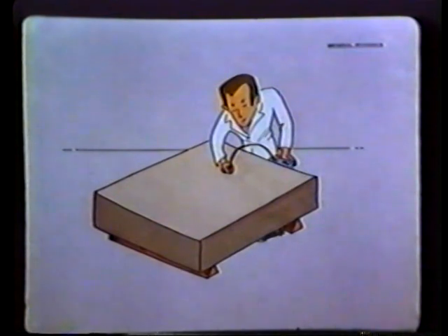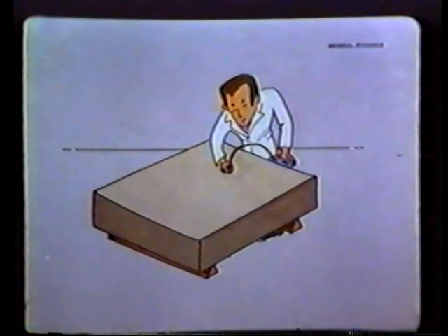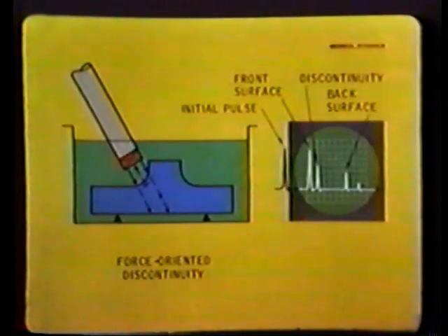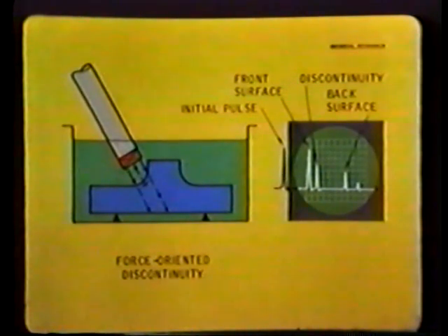The experienced operator develops a knowledge as to what type of discontinuities are likely to be encountered, and where they're most likely to occur. He learns to discriminate between relevant and non-relevant indications. Non-metallic inclusions, foreign material or porosity in a cast ingot may be rolled, forged, or extruded into wafer-thin discontinuities. The forces used in fabrication tend to orient the flat plane parallel to the surface.